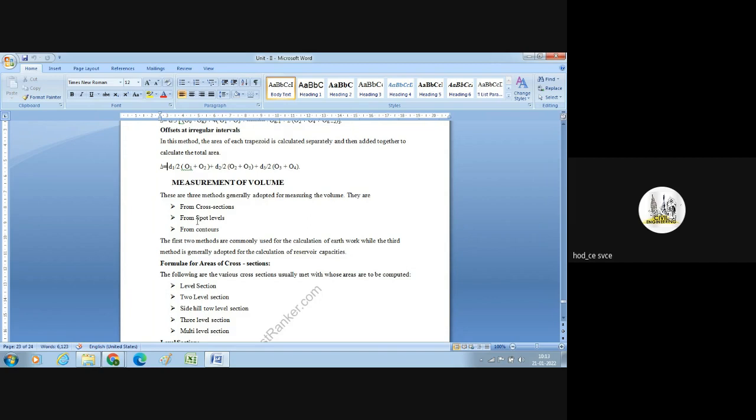Next, area by latitude and meridian distance. Now, as you know, we have calculated the meridian distances M1, M2, and so on. Vertical distance is the latitude, and horizontal distance is the departure, right? Area equals latitude L multiplied by meridian distance M. Then you will get the area. So if you need the area, A equals the summation of L multiplied by M, latitude times M.